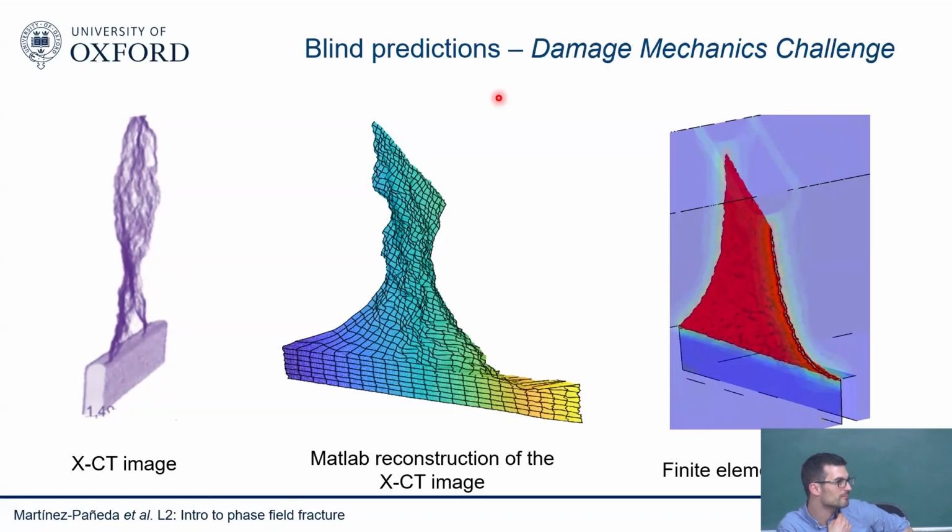So for this length scale parameter material property, if we calculate it from the formula that you have shown, the value generally comes out very high. The length scale parameter value depends on your material. It could come out high, depending on the fracture process. So first we have to decide on mesh size or length scale parameter, which one should we choose first? No, the length scale is a material property, so you don't have the freedom to pick that one. If you have a given material and you want to be predictive, you need to take the value that comes out of the equation. And then what you pick is your h.